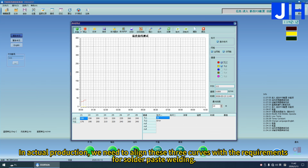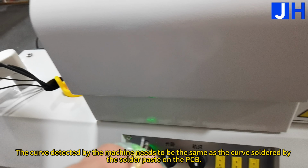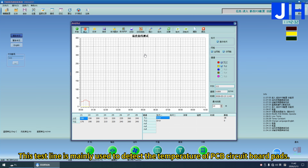In actual production, we need to align these 3 curves with the requirements for solder paste welding. The curve detected by the machine needs to be the same as the curve soldered by the solder paste on the PCB. This test cable is connected together, don't break it. If it is disconnected, it will be difficult to connect together. This test line is mainly used to detect the temperature of PCB circuit board pads.